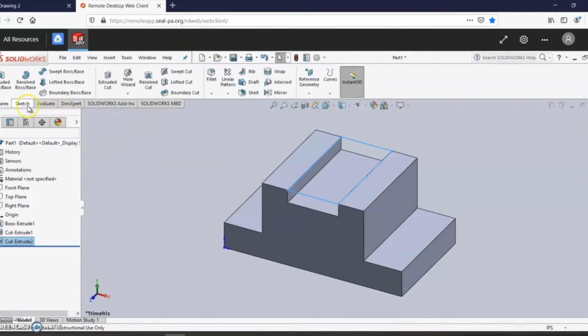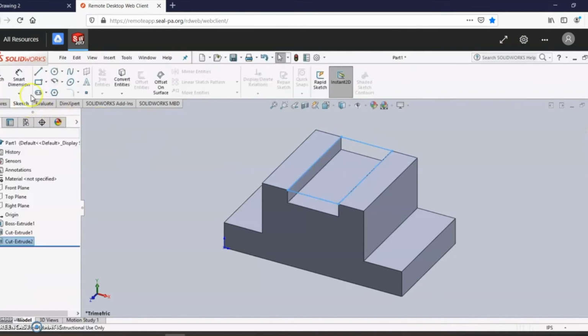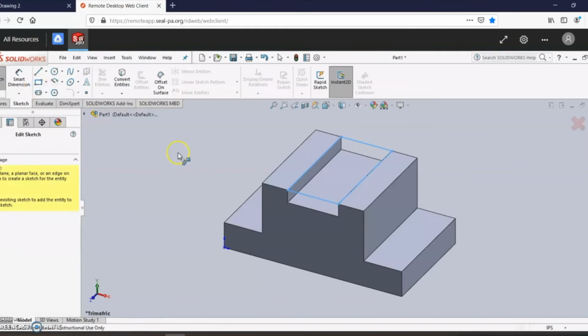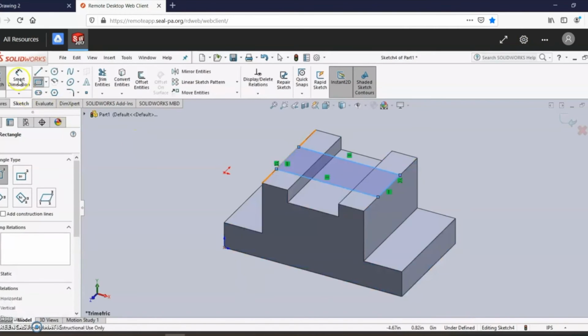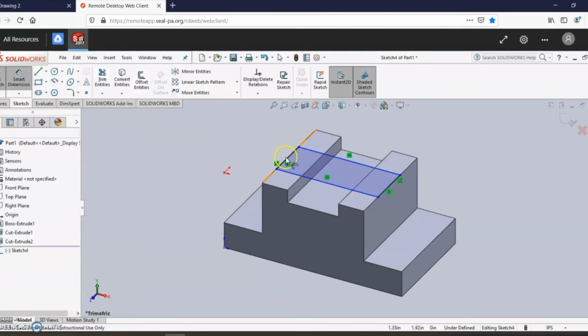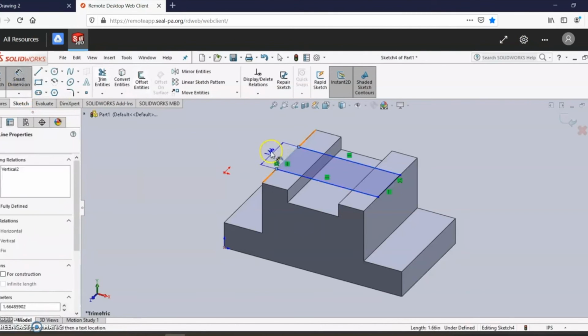Now, next step, Sketch, right back to the first step, Sketch, choose the shape. This plane and this plane, it's the same plane, so it doesn't matter which one you click. Make sure you don't start or end on your midpoint, so just find it and move away. It's in here somewhere. There it is. So just move away. And it's basically the same as the other one, the same dimensions, just indexed 90 degrees.